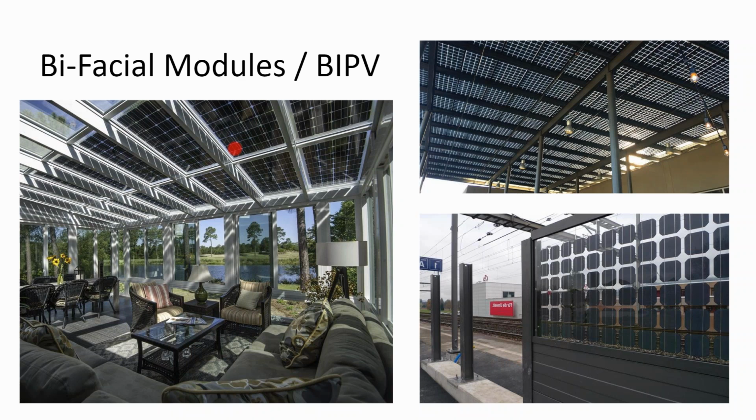And so a bifacial panel should give a system another 10% boost compared to their non-bifacial peers, but not when they're put directly above a roof surface, mainly because the spacing between the cells is so close together, but it's not cost effective to space them further apart, because then you're buying more non-solar material for your buck. And so these bifacial panels make great architectural statements. This sunroom, this awning, all that stuff's pretty cool.